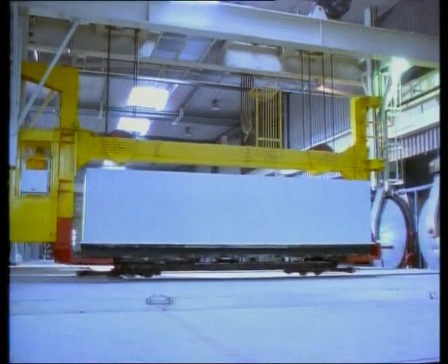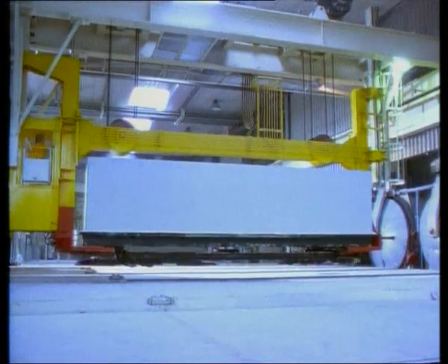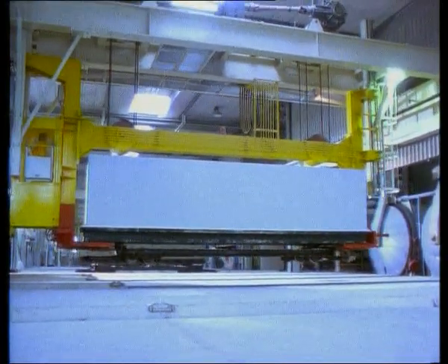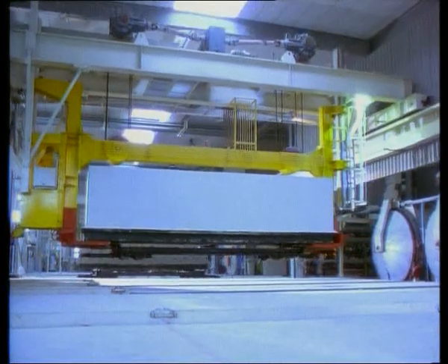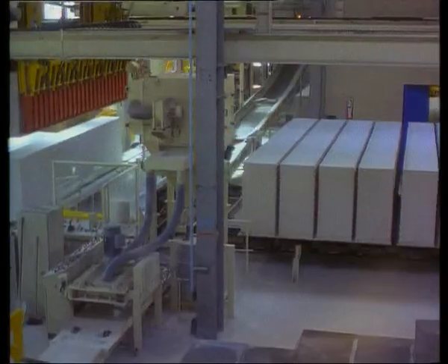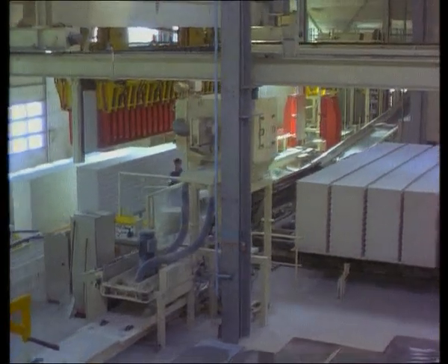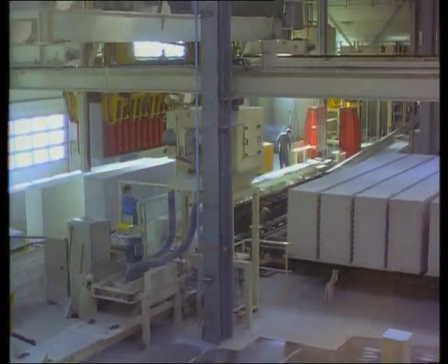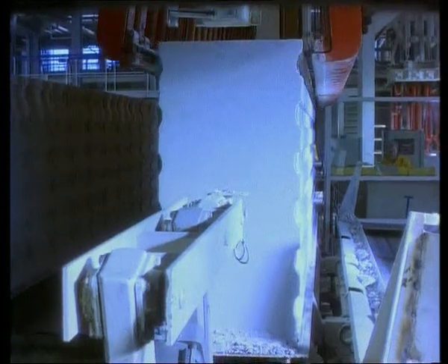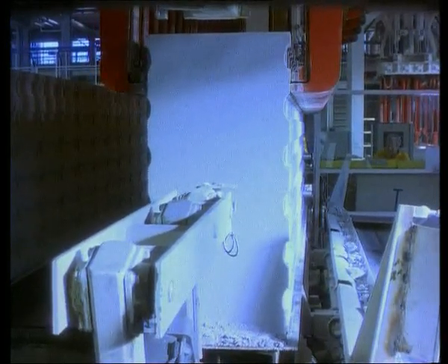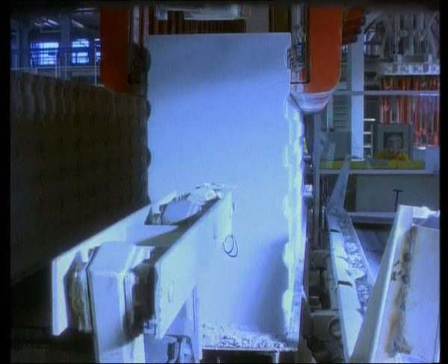The autoclave crane then transports 3 cured cakes at a time into the unloading section and places them onto the cross-chain conveyor in front of the separating crane. In the first step of the unloading process, the individual layers are separated and the compressive strength of the blocks is tested.